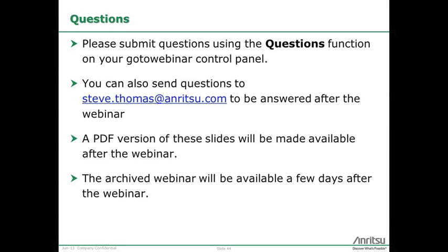Otherwise, you're dead. Maybe to amplify a little bit there, the Olympics is maybe even worse than an NFL situation because of so many things going on. It might be handy to have multiple people available, and coordinating between two people looking for an emitter can make the process faster. For example, if you can take two bearings with two people, you can do that all at once rather than having to travel between the locations.